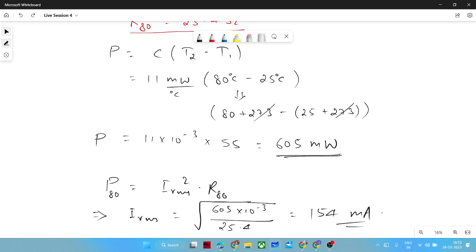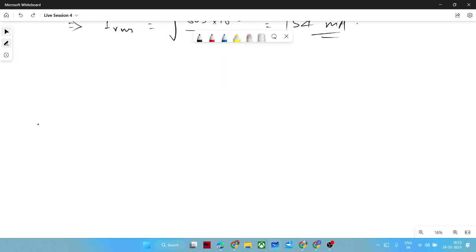Yes, because of that resistance. That is not the drawback of a resistance. It is really good at dropping the voltage and it will definitely protect your circuit. But the drawback is that as you move to the steady state condition, your resistance value is the same, so the drop keeps happening. Let us assume your input voltage is 325, and the drop across the resistance is 150 volts.